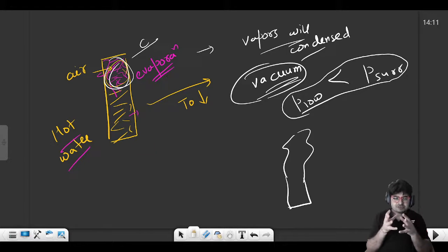When you apply those processes of molding, blowing, etc., the shape of the polymers changes. Because of that shape change, the molecular orientation may get affected. Residual stresses may get developed, meaning internal stress may get developed. So due to the heating or something like this, वो stress release हो सकते हैं that can cause the shrink of the bottle. Otherwise, softening and deformation you can use to define this. Otherwise, you can also talk about the glass transition temperature if you know the difference between thermosetting and thermoplastic polymers. So you can use the concept of glass transition temperature.